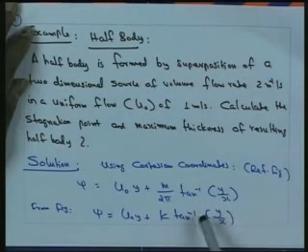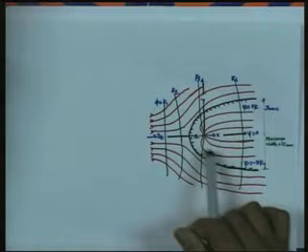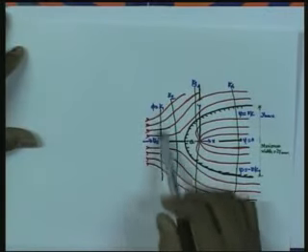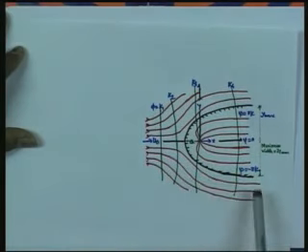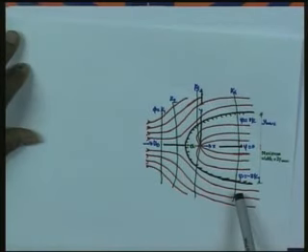If m by 2 pi is represented by k, we can write psi is equal to u0 y plus k tan inverse y by x. In the figure, we have the equipotential lines k1, k2, k3 etc., and the streamlines, and the potential lines are drawn for various values.